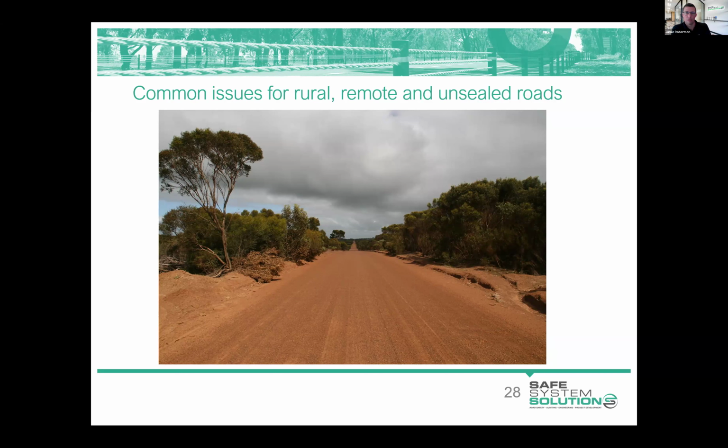The locations that present the greatest risks on roads like this are those locations where something changes. So it's a curve after a long straight. It might be a section of road where there's variability in the surface that drivers need to be warned of. So delineation and signing treatments are what we commonly go to. So it might be advanced warning of a curve or delineation of a curve, warning of a dip in the road or a section where the surface is rough, and this type of thing.